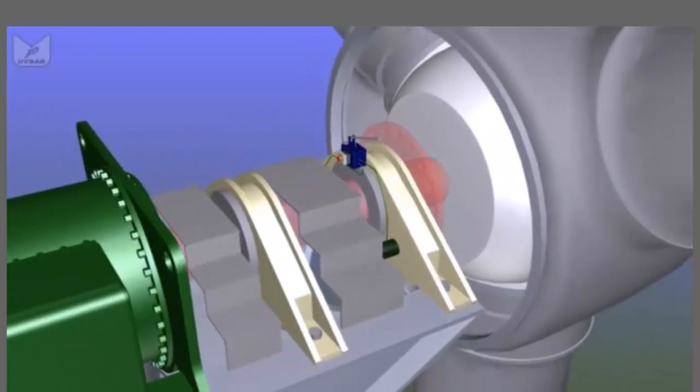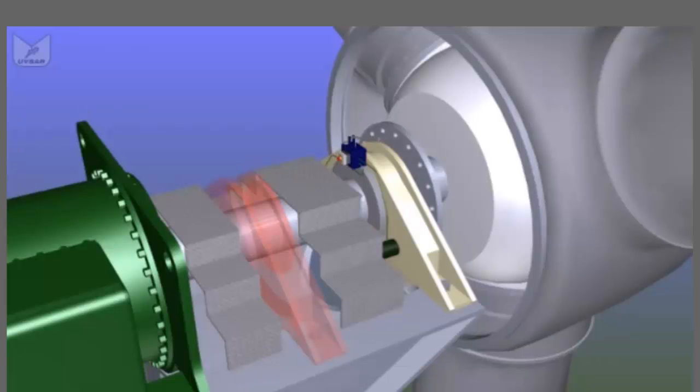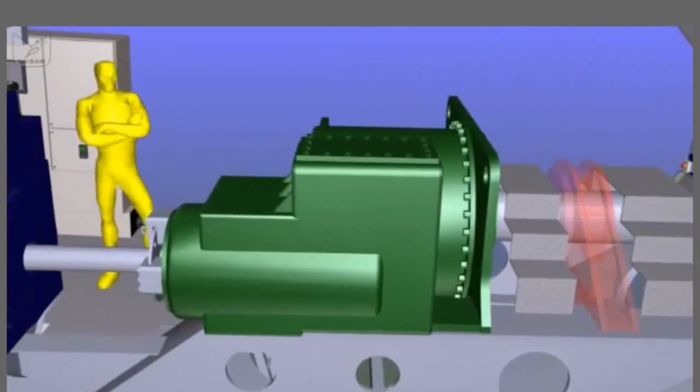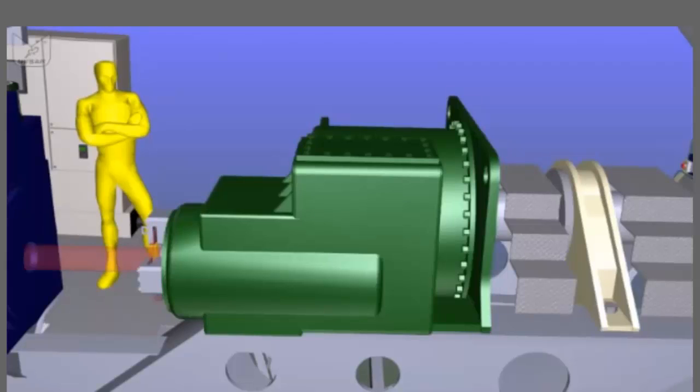And we have a couple of pins on the first bearing that lock the main rotor in position if we need to access the hub. It's a safety feature. If you're in there and it starts rotating, it gets scary. So our main shaft drives our gearbox, which is mounted centrally because it's often the heaviest component.